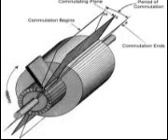Field frame. Figure 9-8: increasing the number of coils reduces the ripple in the voltage. The field frame is also called the yoke, which is the foundation or frame for the generator. The frame has 2 functions. It completes the magnetic circuit between the poles and acts as a mechanical support for the other parts of the generator. In figure 9-10, the frame for a 2-pole generator is shown in a cross-sectional view.